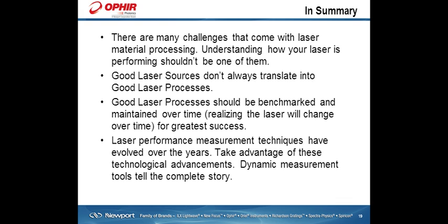And to be honest with you, understanding how your laser is performing should not be one of your problems, all right? There are so many different products and modern-day techniques out there for collecting information on the dynamic changes in your laser system that this really should not be a problem, understanding your laser and understanding how to manage those parameters. Good laser sources don't always translate into good laser processes. Again, there are a lot of high-quality laser sources being provided, but that doesn't necessarily mean that the overall laser system is going to be a good one, even if you are getting a good laser source.